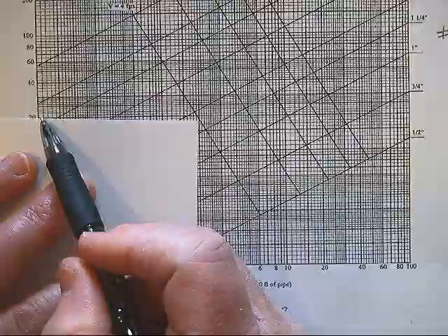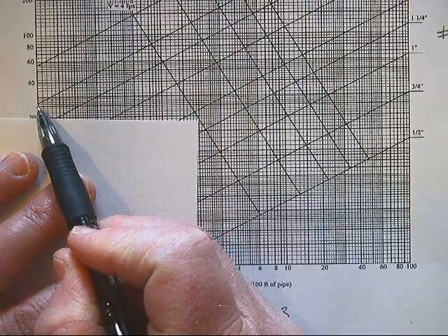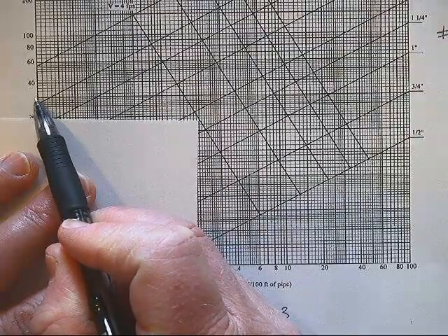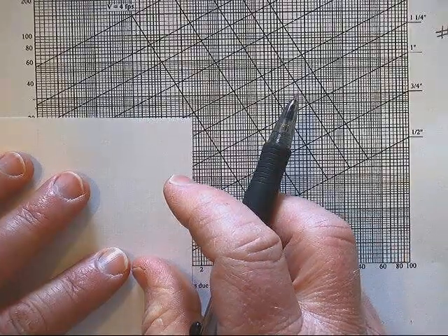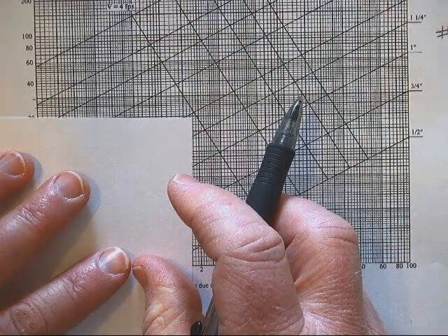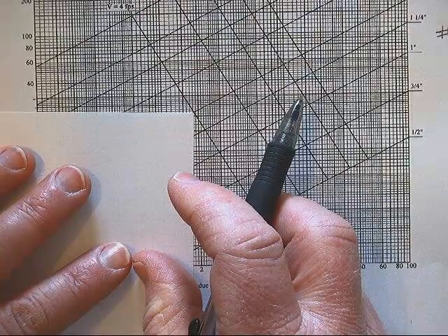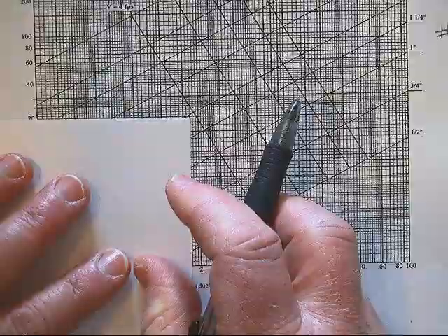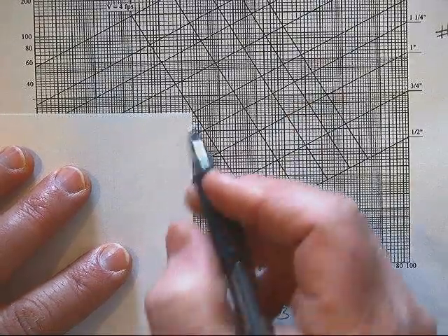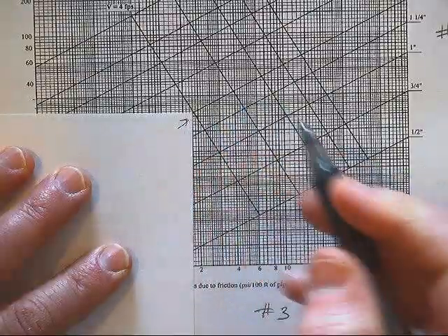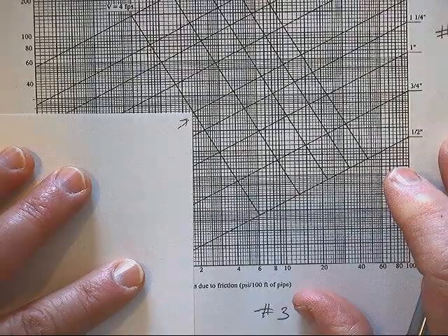And so what I'm seeing right here is that this is 20. This darker line right here will be 25, and then the next dark line right there will be 30 gallons per minute. So we're going to go to 20, and then for this example, we're just going to go up 2 lines. Okay, we're going to call that 22. So 1, 2 lines. And now we'll take this corner and intersect it with a 1-inch service. So we'll slide across.